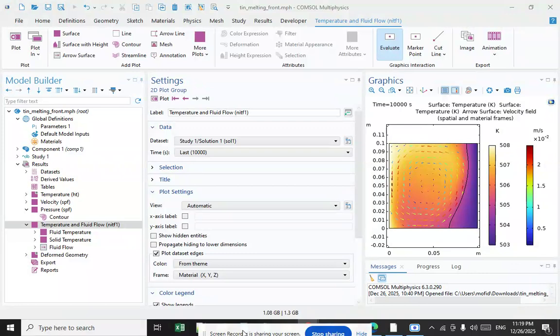The martensitic transformation occurs as one of the many phase transformations in carbon steel and stands as a model for displacive phase transformations. Order-disorder transitions, such as in alpha titanium aluminide, are another example. As with states of matter, there is also a metastable to equilibrium phase transformation for structural phase transitions. A metastable polymorph which forms rapidly due to lower surface energy will transform to an equilibrium phase given sufficient thermal input to overcome an energetic barrier.